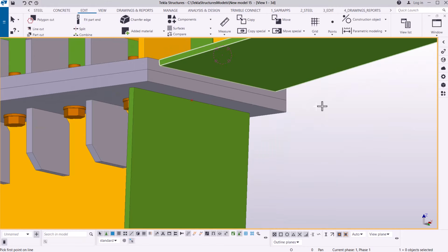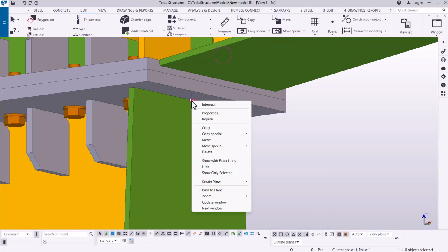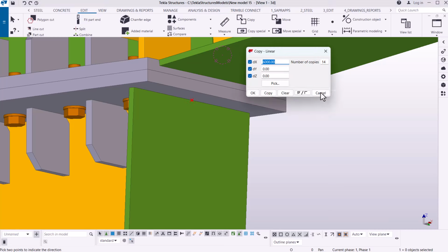Now I'm going to offset this point downward by 1500 millimeter. So I'm going to select it, then come to special copy here. Then under copy, I'll pick linear. So then under linear, I'll come to z-axis and take into account the position of the z-axis here. You can see it's pointing upward, but this time around we're moving downward. So we have to prefix that dimension with a negative sign because we are going against the direction of the z-axis. So I'll key in 1500 there.